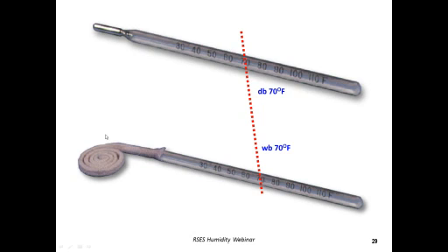It's obvious that if the dry bulb and the wet bulb are the same, with air passing across it, we're not able to evaporate any moisture off of our wick. So by not being able to evaporate any moisture off the wick, that tells us that our air is completely saturated.